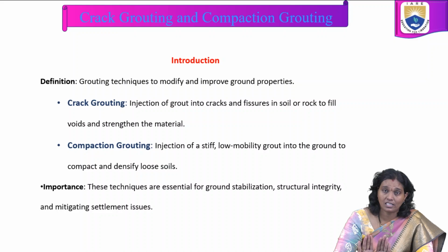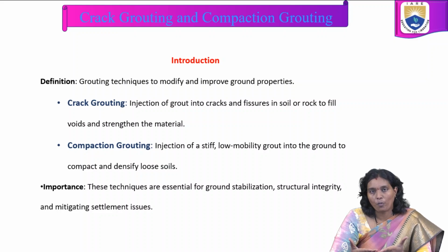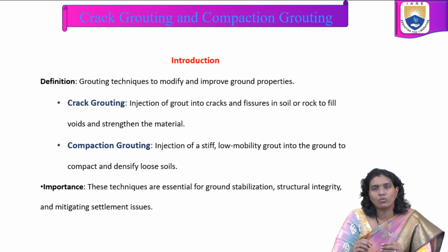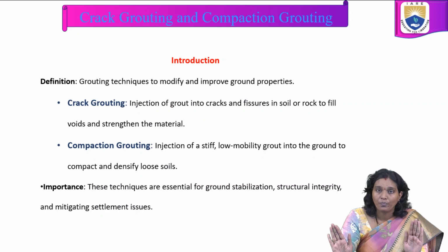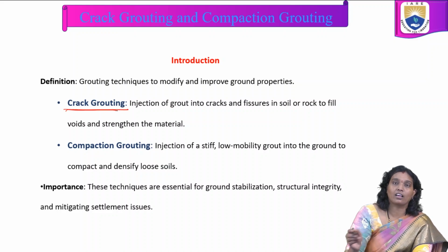And also before construction, if any soil disturbances are there, we can improve their properties by using these grouting techniques. We inject the grout and give the soil the desired properties for better infrastructure. Whenever cracks are there, we fill those voids and strengthen that particular material. Such a type of grouting is known as crack grouting.